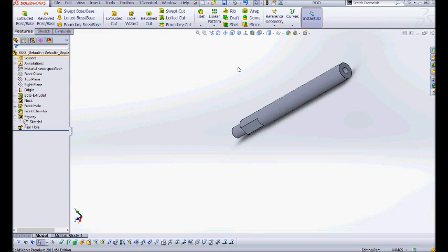Okay, so now what we want to do, you want to go to features. You want to go extruded cut, put a check on the left side of cut, change this to 10, green check. Okay, so now we've got things settled on the home front. We've made the design change our boss asked us to make. It's time to reclaim our children.